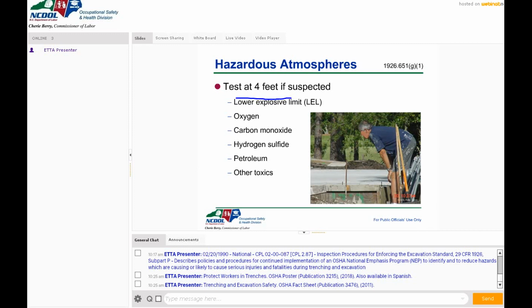Zachary, no, that's not considered a confined space on trenching excavation. That's a common question we get an awful lot. If you're doing trenching excavation, you fall under that standard. If you are climbing into, say, a manhole in the excavation site, which there should be a demonstration coming up in a little bit, as soon as you enter the manhole, or better yet, the pipe that is down in there, say you got a 6 foot sewer line that you're laying and you go inside that pipe.